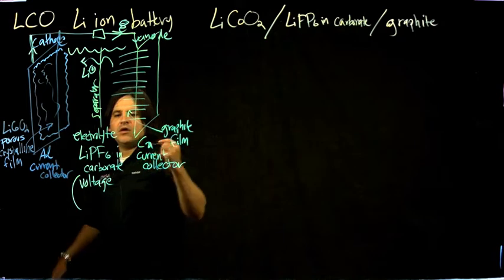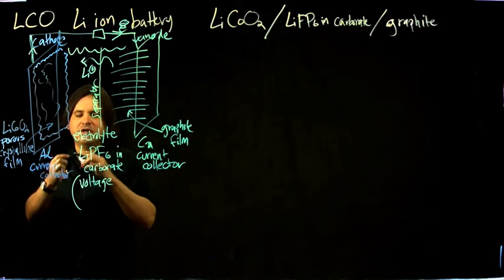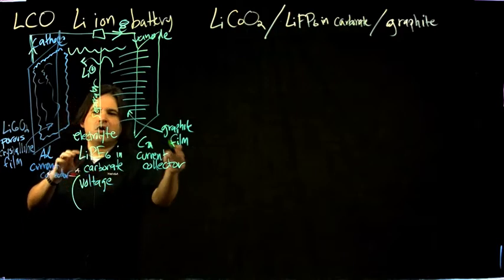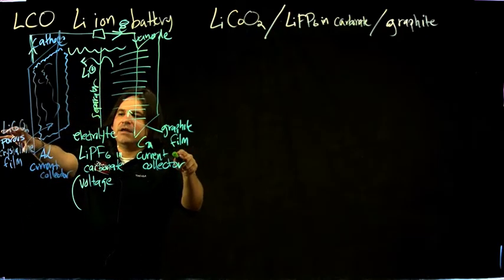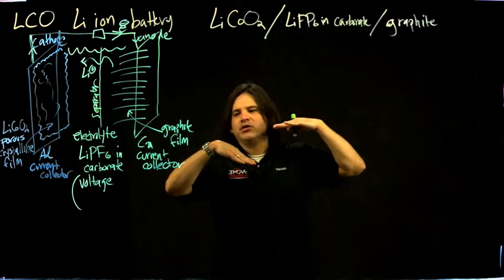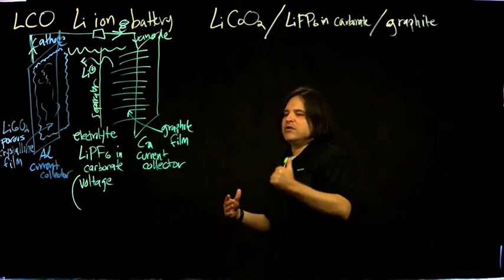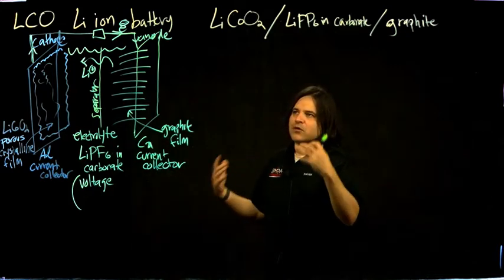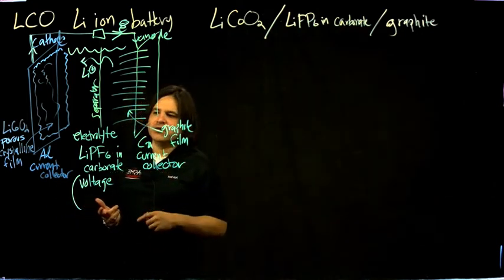So the window, each of these materials operates within a certain voltage. So this combination of carbon, this graphite and lithium cobalt oxide, that voltage that naturally gets set up by its standard reduction potential and the Nernst equation, the open circuit voltage, is a bit over 3 volts.